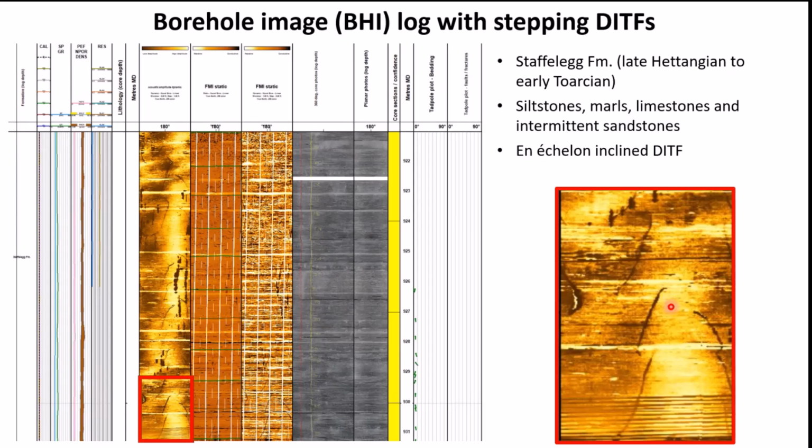The reason why it's important to play around is that quite often you don't get a centerline fracture. Quite often you get stepping fractures, kind of en echelon arranged fractures. The different mechanisms, obviously, you can think about: well, the borehole is not aligned with one of the principal stress axes, or there's anisotropy, etcetera.